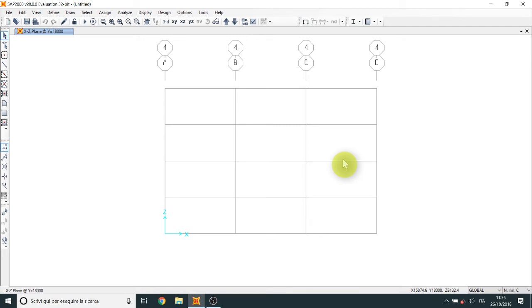This is a classical steel structure with the bracing. You will see a lot of these structures if you become a designer of steel frames. Another type can be this one. This is the so-called bracing tower. For the seismic rule, you need bracing in your structures. You need a concrete core, or instead of using concrete walls or a concrete core, you can use a bracing.